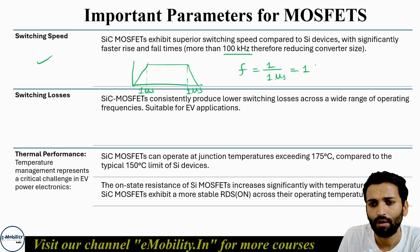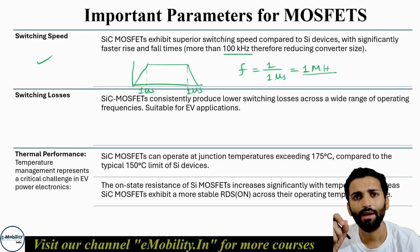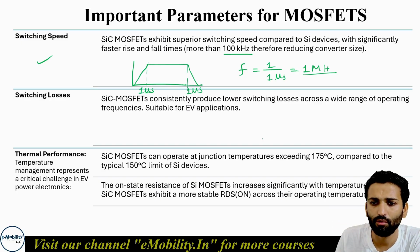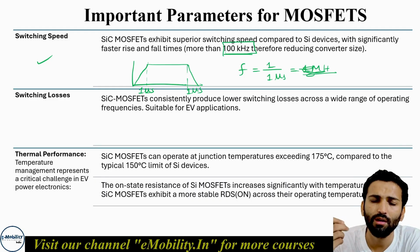It is 1 megahertz. So that means the PWM frequency which we can apply to the MOSFET for the switching is 1 megahertz. Usually this is a very high frequency. Usually MOSFETs work in a range of 100 kilohertz or more than 100 kilohertz. Some MOSFETs which are smaller in size can work at around 1 megahertz.